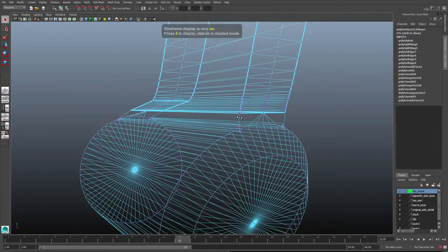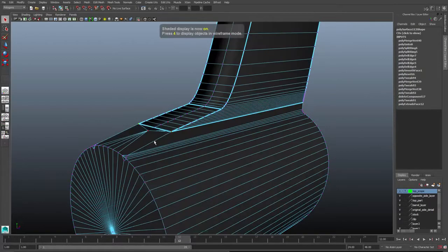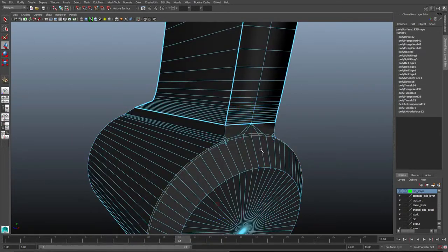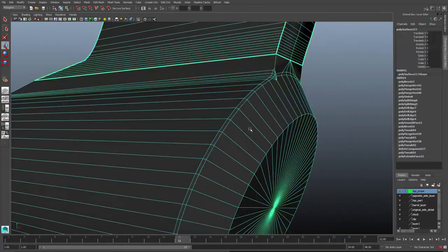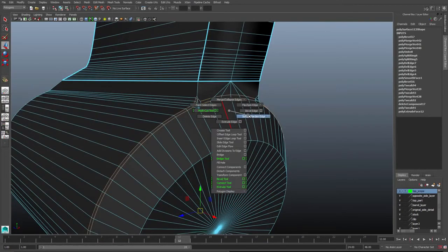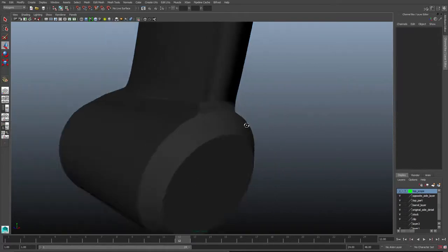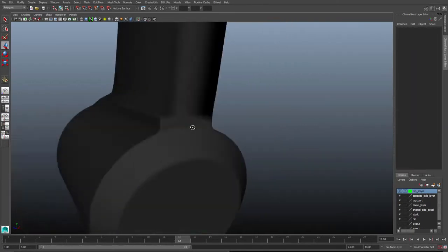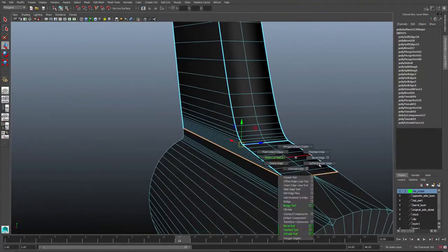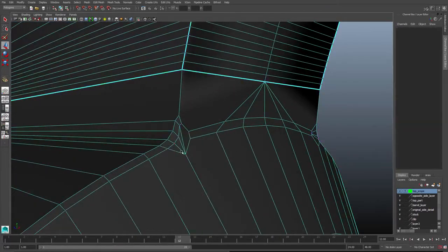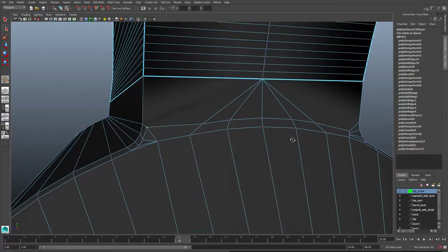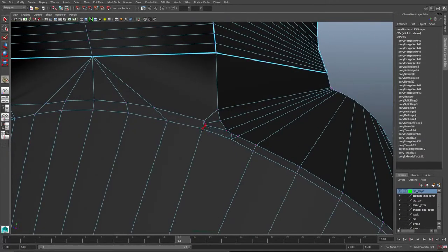So the angle where the cylinder meets the flat part, I add a little bit of bevel. Around the cap faces at the cap of the cylinder, I'm going to add a bevel. And in most cases, I'm adding relatively narrow bevels. This will create a sharp highlight in the area. And that sharp corner highlight is really one of the keys to making our hard surface objects look tactile. We want the viewer to feel like they could reach out and touch our object.